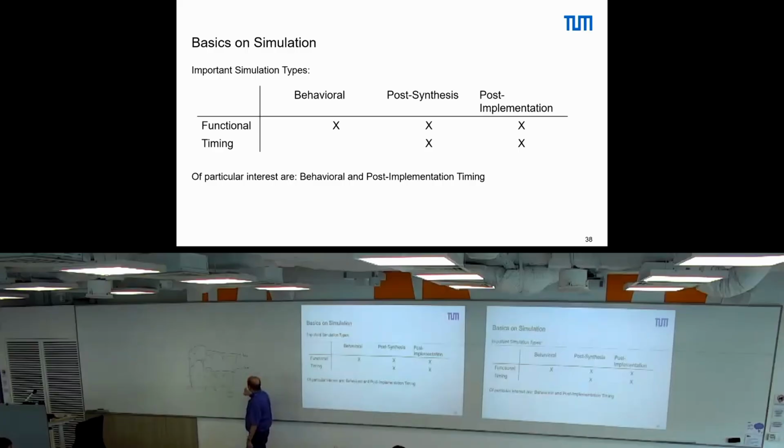So for the minimum, the fastest path here is 0.8 plus 1, which is 1.8, plus 1.1, which is 1.9. The path here through the OR is 1.1. The path through the AND is 1 nanosecond. So the shortest path is this one. Most of the time in the exercise we will not have this range. We just have one fixed value for each delay.